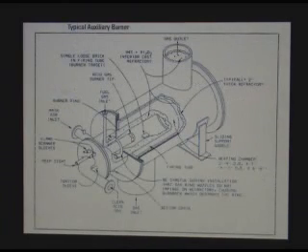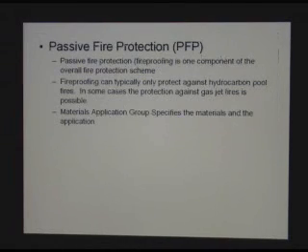This was our section on refractory, and now we go to passive fire protection. We are only involved in specifying the materials to be used. We don't get involved in the extent of the fireproofing. This is done by Mechanical Utilities Group. But fire protection is only one component of the overall protection scheme, and it only protects against hydrocarbon pool fires. You cannot protect against any gas explosion or gas fires with fireproofing. It's strictly for hydrocarbon pool fires.